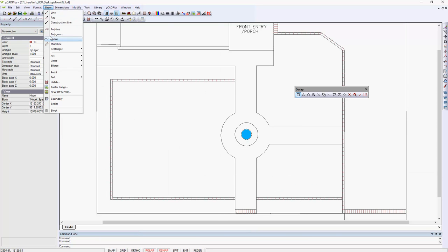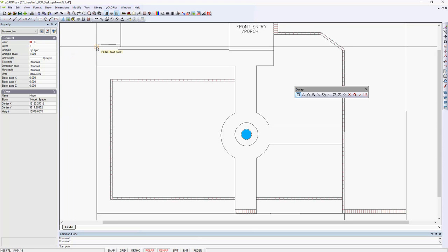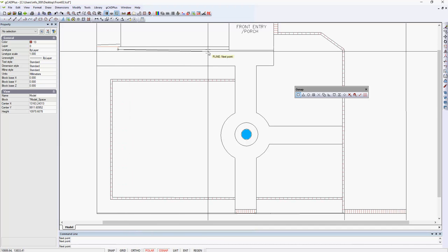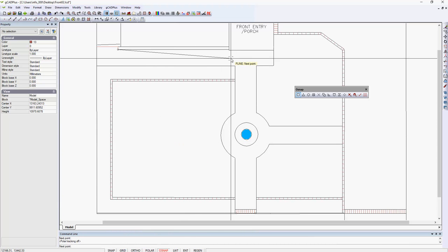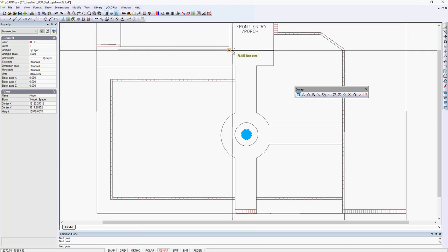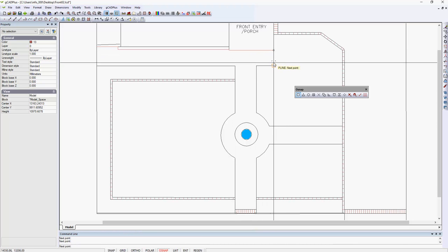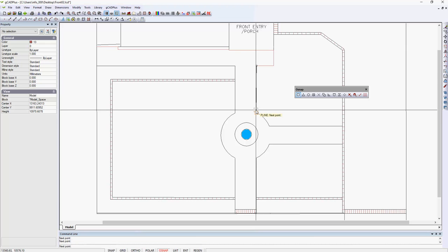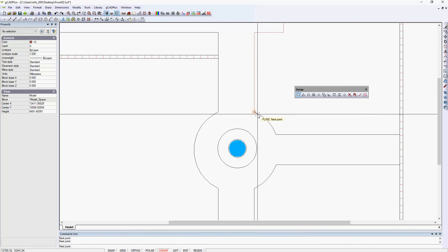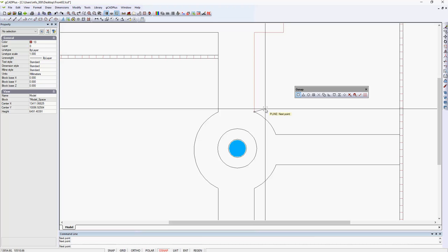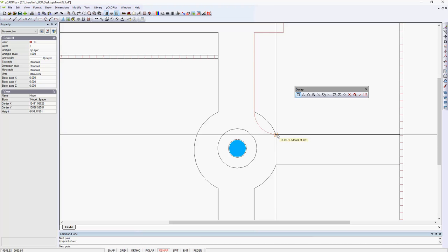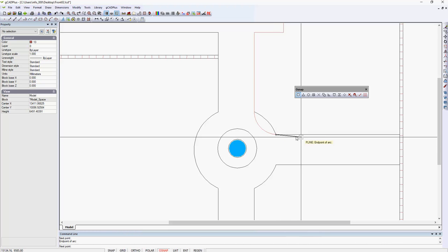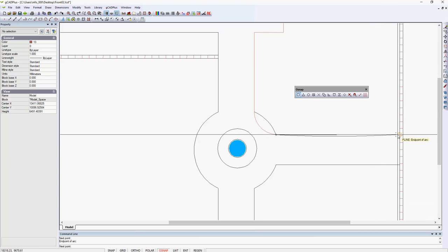Let's start the polyline command, and we'll start up here in the corner, and you see that as I move it is relatively easy. I'll take polar off at the moment. It's relatively easy to find even tiny variations in where the polyline is, but when I reach this point here I need to go into arc mode within the polyline itself, and we'll pick arc and find that endpoint. Notice how the arc is not placed correctly yet. We'll attend to that in a moment.